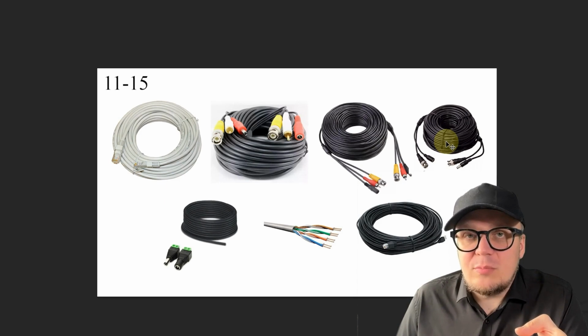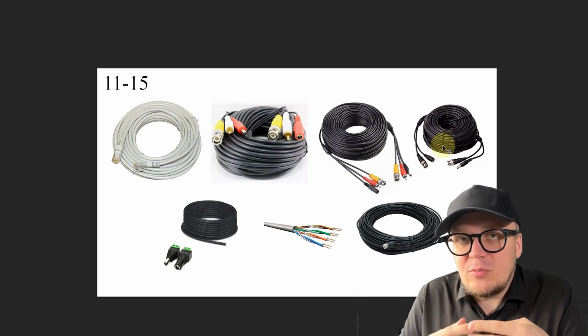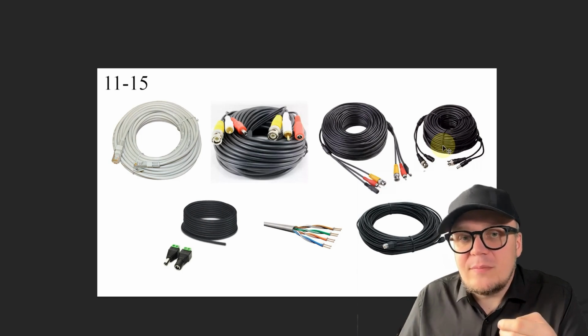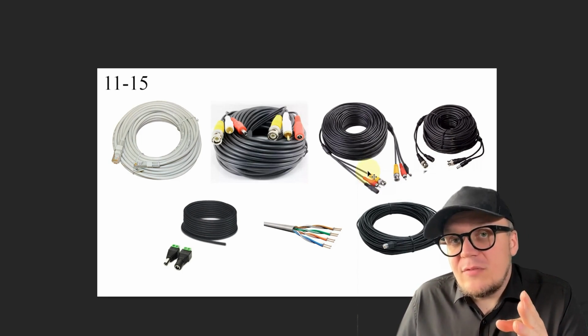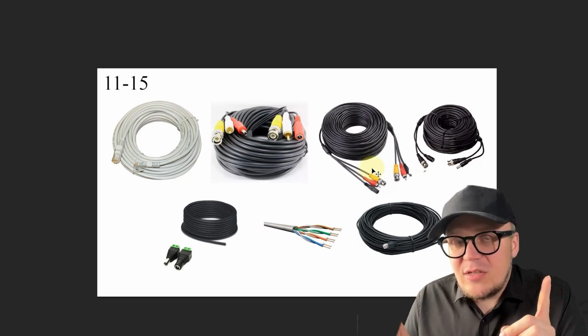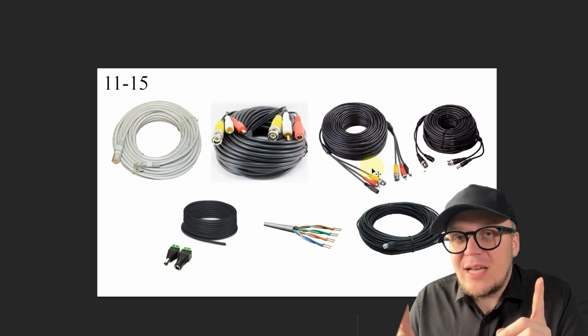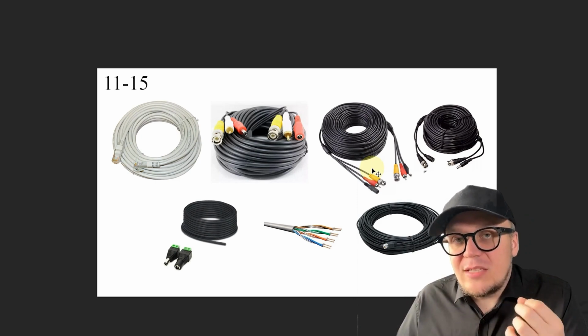People think they have bad equipment and contact the store for warranty service. In the store, they connect it with a proper cable and everything works perfectly. It's a very common situation, also common when you need to install, for example, 6 cameras. 5 of them will be at a distance of 20 meters, 25, maybe the 6th camera at a distance of 40 meters, 50 meters. And you need to understand that a 20-meter cable and a 50-meter cable are 2 different cables. That is, a 50-meter cable should be of higher quality with a thicker core.